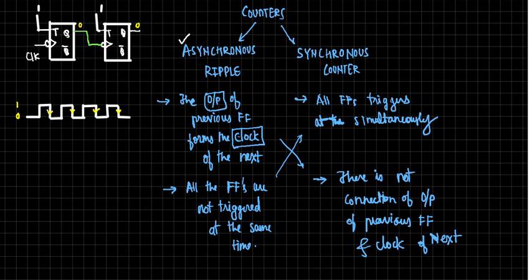It was 0, right? So I am drawing the waveform for this Q, the first flip-flop's waveform. It will be 0 initially. How long will it be 0? Till the edge comes, right? Then it will turn to 1. It will retain 1 till the next clock edge comes. Then it will go to 0. Then it will maintain 0 till the next negative edge comes, just because it's a negative edge triggered flip-flop, and so on. Is that okay? Fine. Now let me write that, Q 0 0 1 1. So it is for Q.